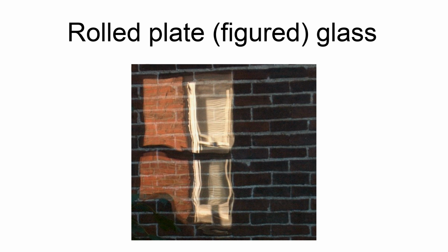The much less common double-rolled figured glass, where the pattern is embossed into both surfaces, cannot be made into a safety glass but will already be thicker than average figured plate to accommodate both pattern faces. The finished thickness being dependent on the imprinted design.